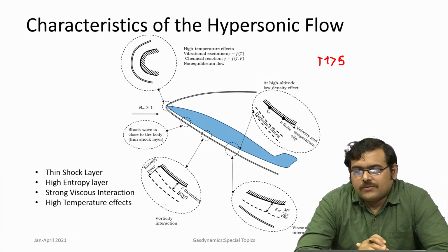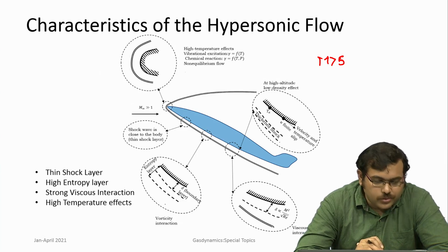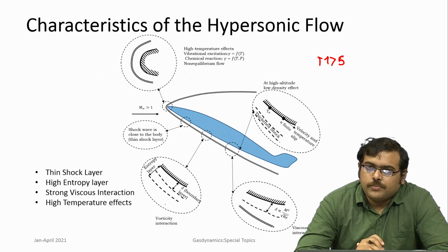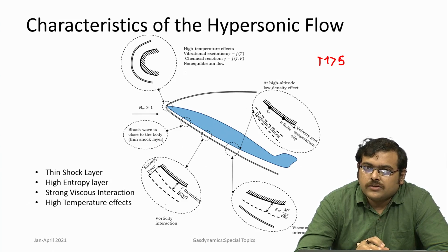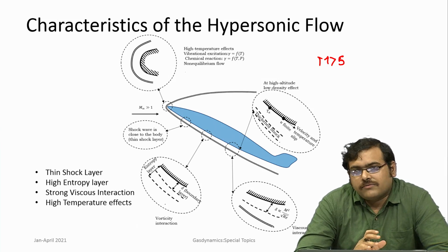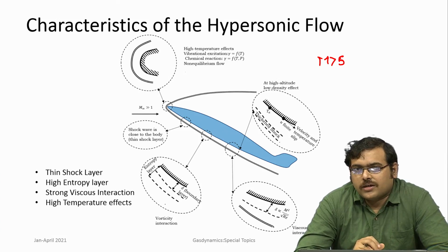But hypersonic flows also provide some kind of simplification which you cannot do in supersonic flows, precisely because of thin shock layers and so on. There are approaches where the coefficients or non-dimensional numbers become independent of Mach number, which is known as Mach number independence, and this can be demonstrated just by looking at the oblique shock equations.